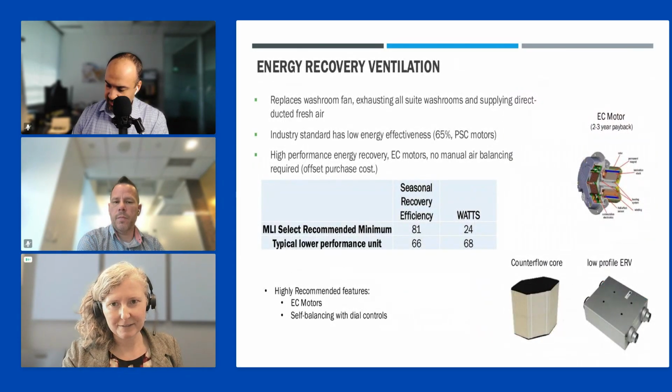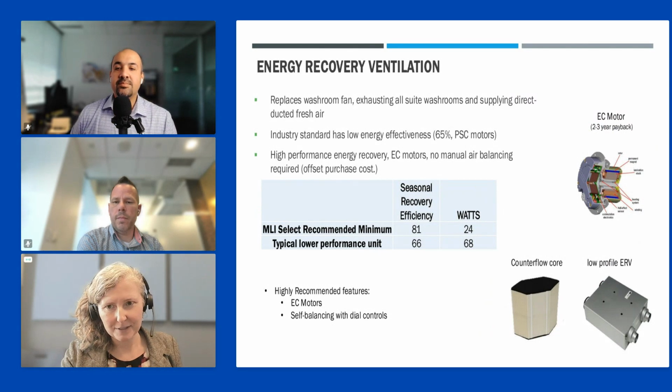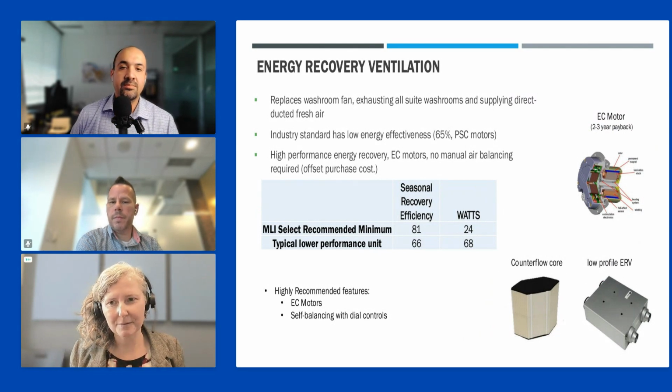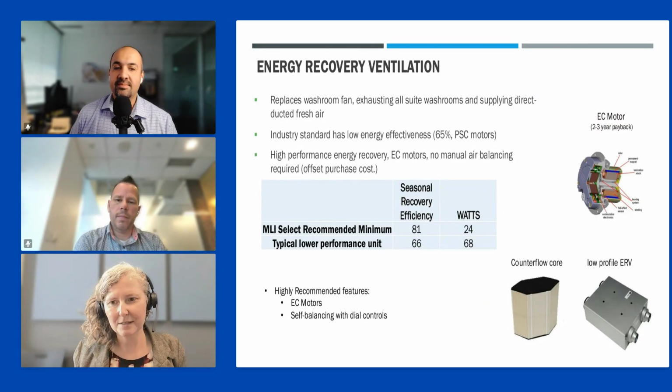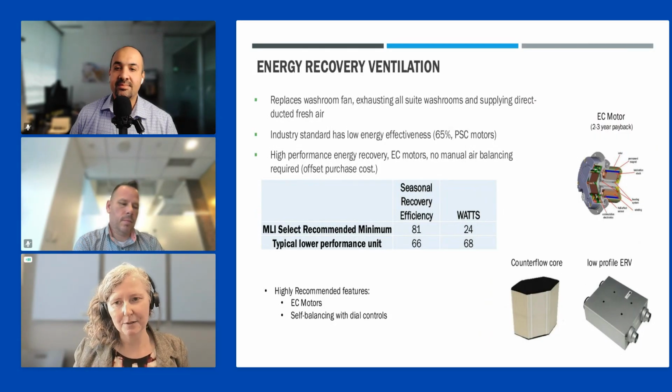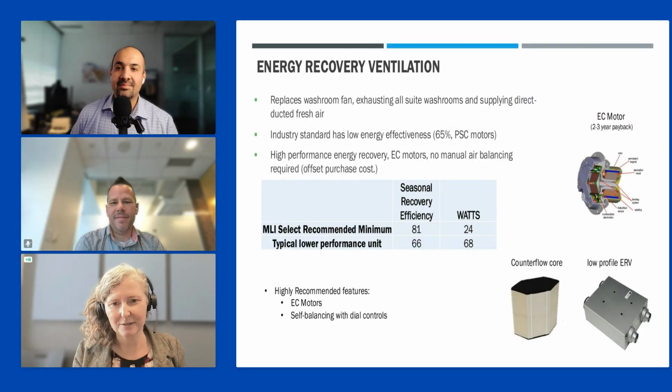Energy recovery ventilation, obviously very important. I think most people will be familiar with this. It's incredibly necessary because it gets fresh air directly to suites. Since 2016, the fire code really tightened the amount of gap around a suite door, so we haven't really had reliable ventilation from a corridor to a suite. There's a lot of reasons we don't think that works anyway, but it especially hasn't worked since 2016. So you've got to duct your air directly to the suite.